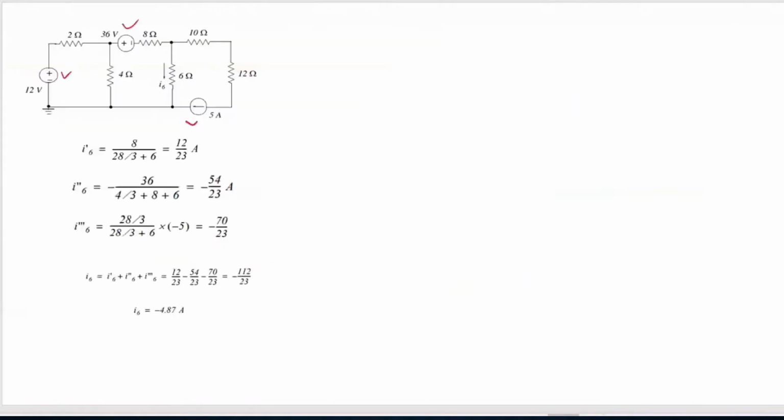Where what is the current source? The current source is nothing but the short circuit current through the terminals, and Rn is the input equivalent resistance. Suppose you have a network like this, and you have two terminals A and B, and you have removed the element between A and B. The equivalent resistance seen from these two terminals A and B into the network is called Rn. So Rn is almost equivalent to RTH.